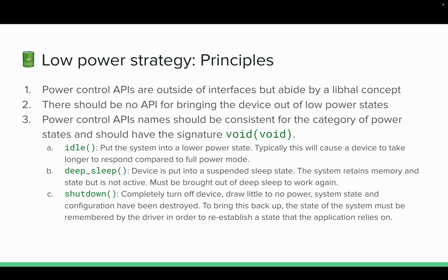And the act of simply talking over the bus to the device was enough. I think it was SPI. We talked over our port, and that wakes up the device when it sees that it's been chip selected. From there, it can come back up and do its work. So I think the rule was to read this register, and if it turns to a 1, then you're good to go. And normally it would turn to a 1 the first time you read it.